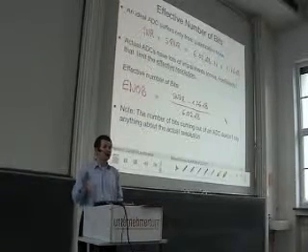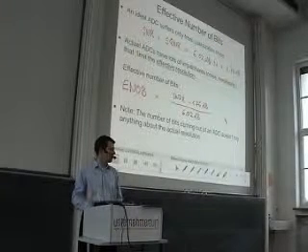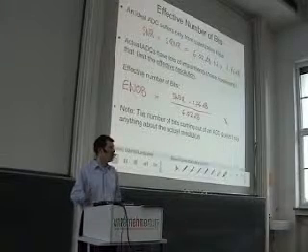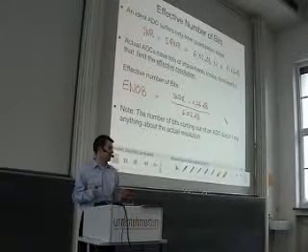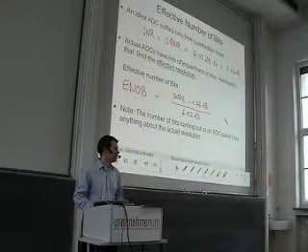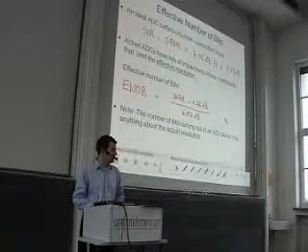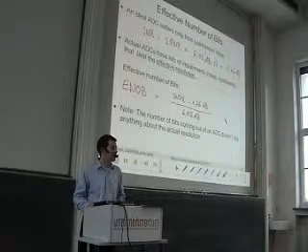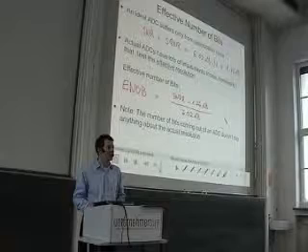Don't look at the number of wires coming out of the device, look at the effective number of bits. Often people do not give the effective number of bits. Then look at the signal to noise ratio divided by 6, then you know how many effective bits you get out of this device.